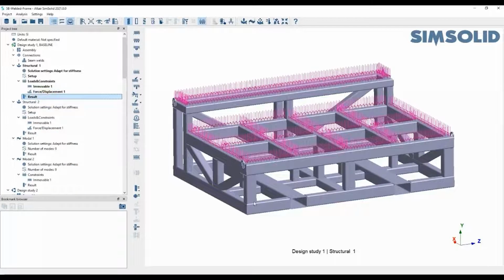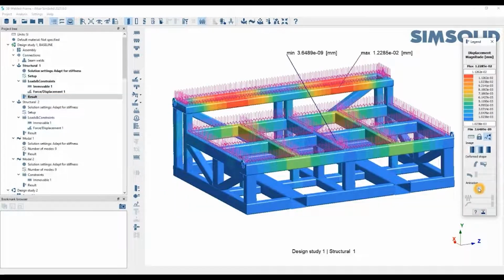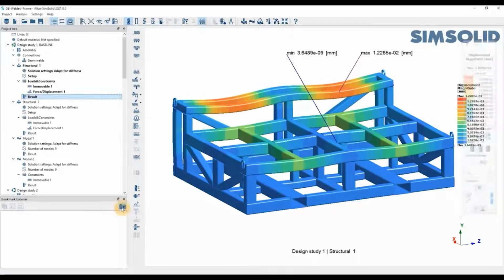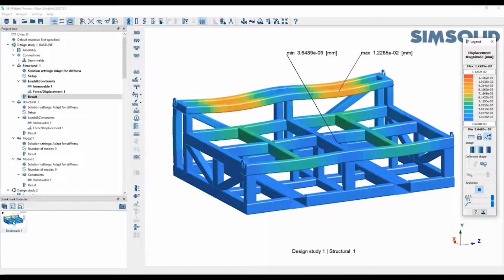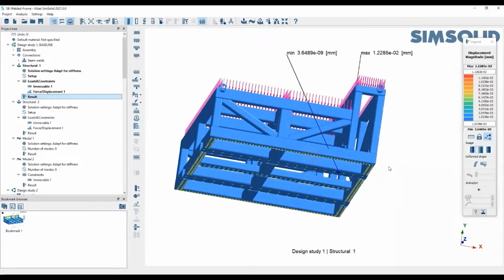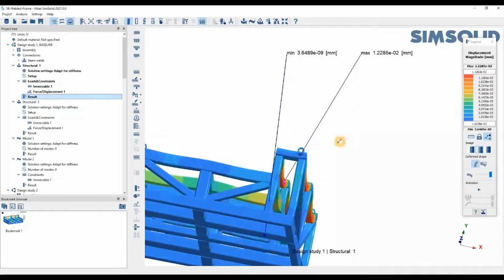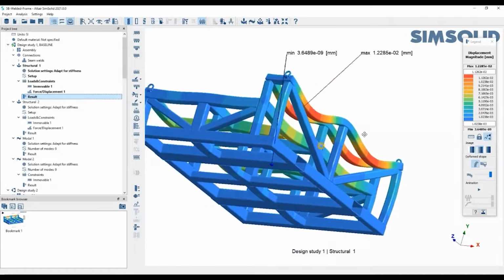And last but not least, I'm just going to show you the quick post-processing of this as well. When you have a moving animation, just click on the camera icon, and because it's moving, it knows to save it automatically as a video. Let's say we're actually looking at, let's make this a bit more dramatic in terms of the scale deformation, and let's say this is the angle that we care about.